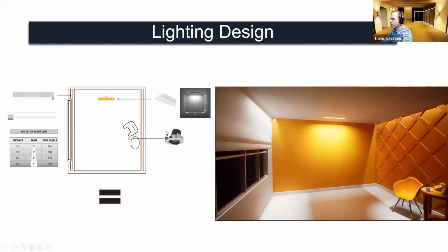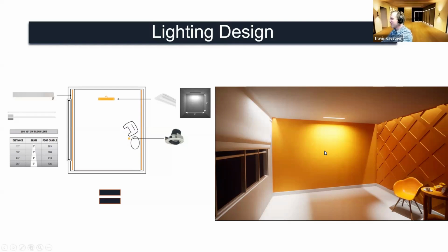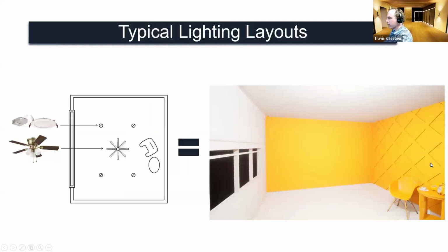Maybe you combine the two and have it on a separate switch. Like maybe it's a fine dining restaurant and you create this atmospheric feeling. Then when your cleaners come in, they just hit the clean button and boom, everything's bright so they can see all the dirt and clean that up. But when people go to eat, it's hidden. That way they can relax in low levels of light, not really see what all's there, just enough to get the feeling. And you can see right here, there's light on the upper part of this and shadow. It draws out the texture on the wall versus where that looked like just a flat wall previously.